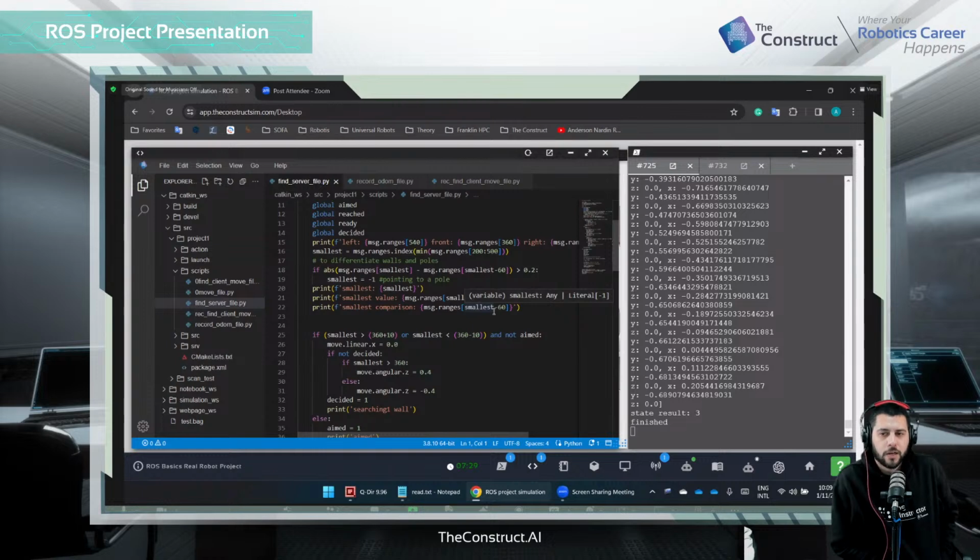Based on the measurement of that sensor, if it is higher than 0.2, I know that I'm detecting something that is too thin. But if it is bigger than that, I mean, the second beam is stopping close to the first one, so it will be like a continuous value. So you know it's the wall rather than an obstacle. Later, if you want, I can do a demonstration. I put it very close to one of the poles, but it neglects the pole because it's interested in walls here.